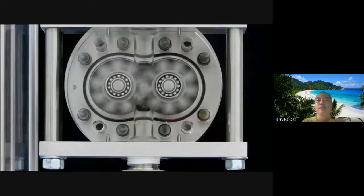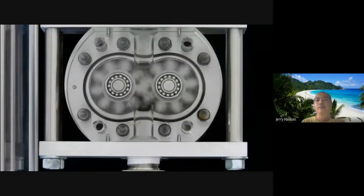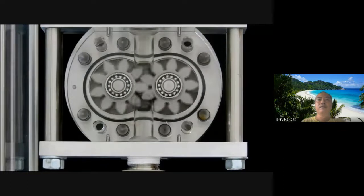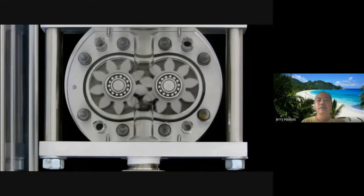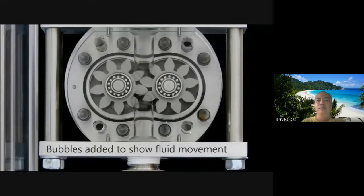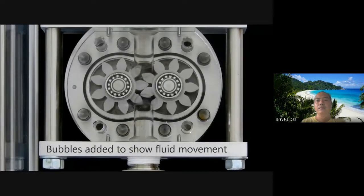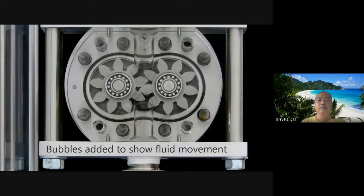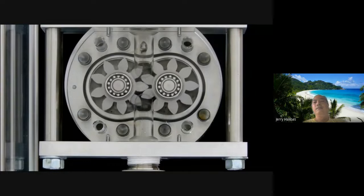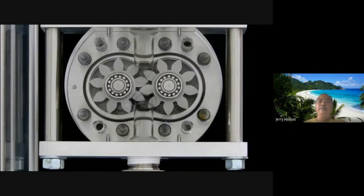Positive displacement flow meters divide a flow stream into fixed, known volumes and count them to determine the total flow and flow rate. In a gear meter, the measurement chamber is created by the gaps formed between precision-engineered gear teeth and the meter's body. As liquid pushes against the gear teeth, the gears progress and isolate a volume of fluid. As liquid continues to enter the meter, the trapped portion of fluid is carried along by the gears until the fluid is released into the downstream side of the meter.